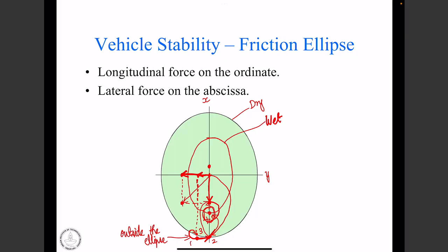Okay, so the anti-lock brake system intervenes only when there is a perceived wheel lock and excessive wheel slip, right? And it tries to ensure that it brings the braking pressures to regions where the wheel slip is manageable. Okay, so that is point number 1. What are other points that we need to look at from this particular graph? Of course, this is a nice graph to draw. We essentially get the mu x and mu y, or Fx and Fy limits, on dry surface, wet surface, icy surface, snowy surface, and so on, right?